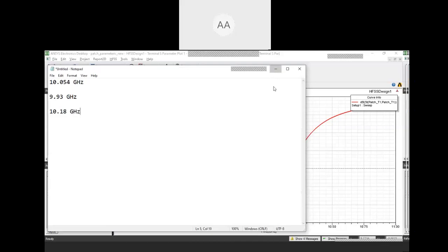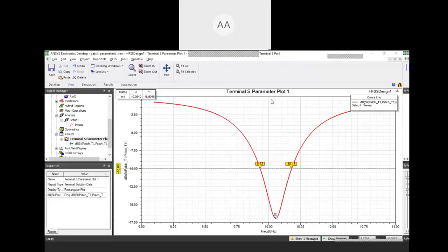So the thing is, you are getting the best of all the things. Fast is fine, but right now interpolating will give you quick results. The most amount of time is taken by discrete, and it gives the best results. Next comes interpolating: it calculates the result at certain points, and on the other points it interpolates the value. In the third case, fast, it calculates the value on its own algorithm and gives you the result. So fast gives you the result in the quickest time, but with the most inaccuracy. Interpolating takes somewhat more time, and the results are somewhat accurate. Discrete results are the most accurate compared to these two, but it takes a lot of time.